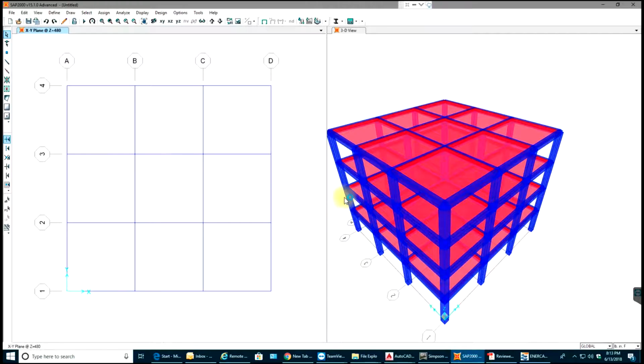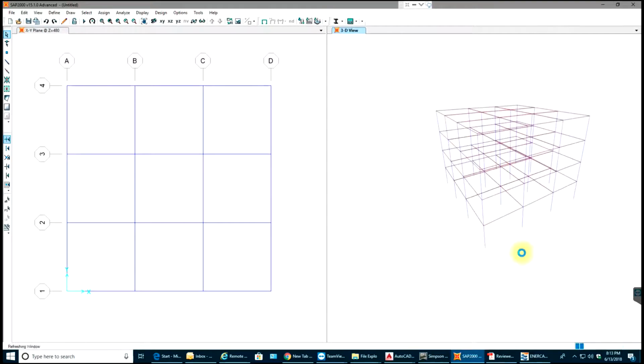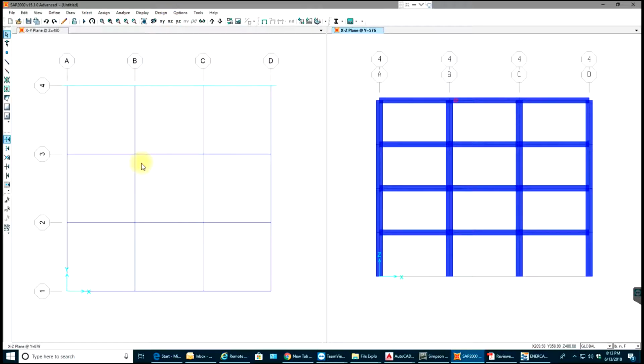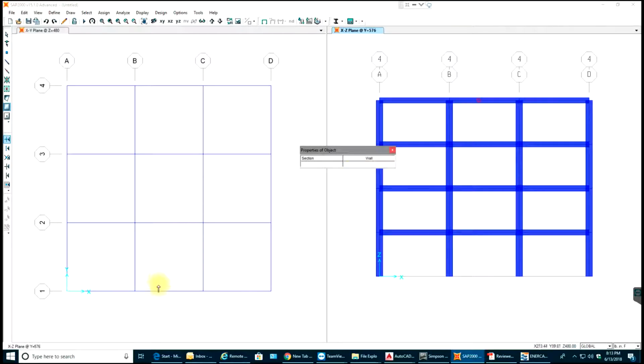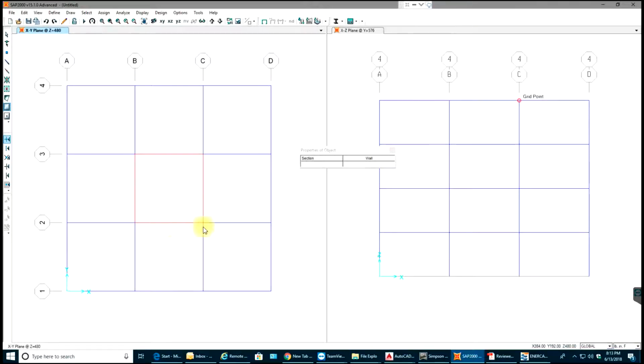That's it. Okay guys, so now the main reason for this video tutorial will be the wind load analysis for area sections. So I am gonna have a wall over here and on the opposite side. So let me go to XZ. Okay, so that would mean I'm having wind load in X direction anyways. Let me go to area tool, select wall, draw your wall. Oh, we don't want that. Control Z.